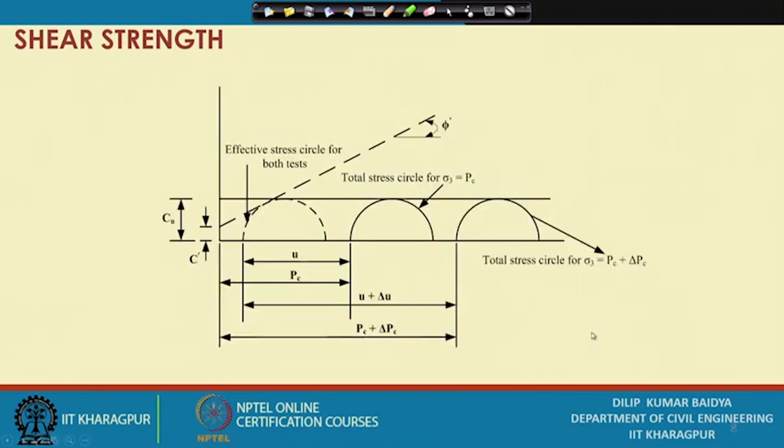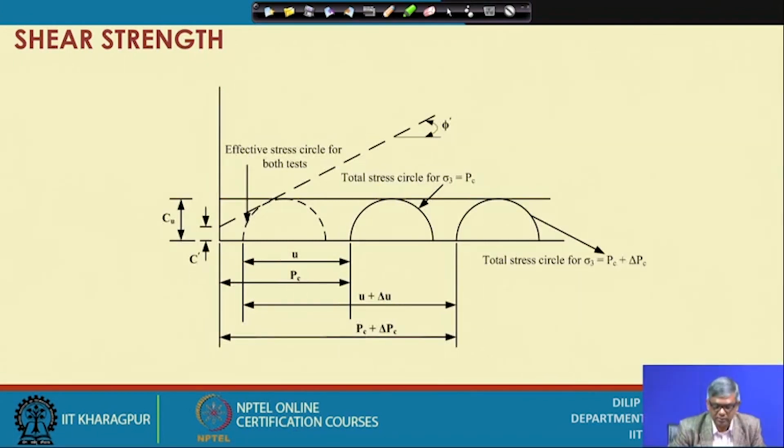And another important observation here: as I have mentioned, when you do an undrained test on saturated soil, the shear strength is constant.